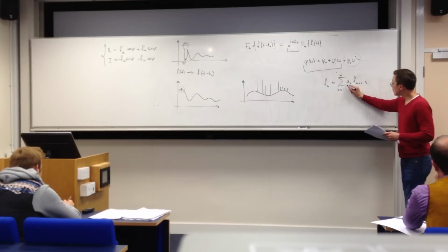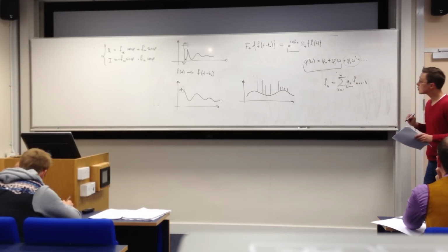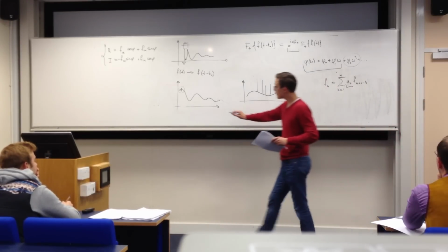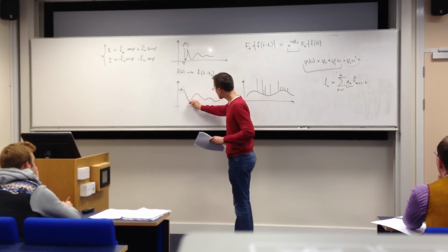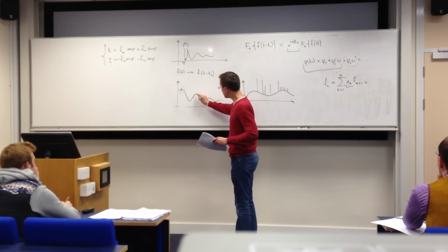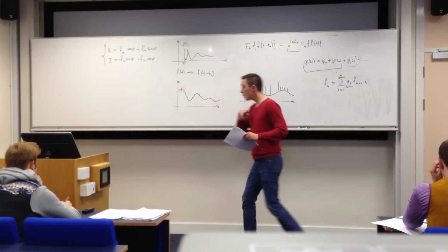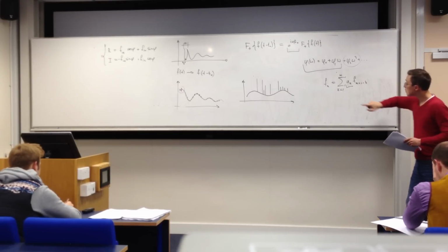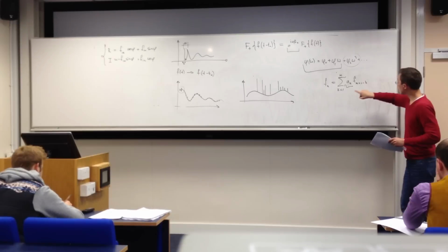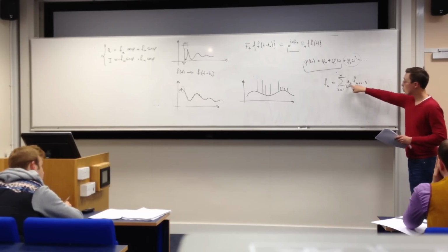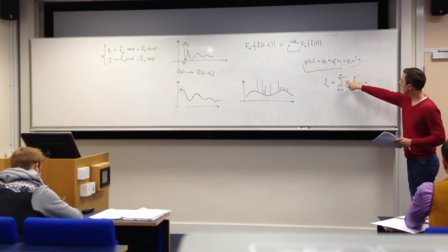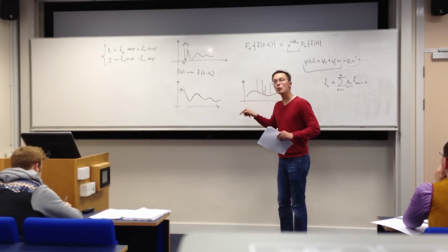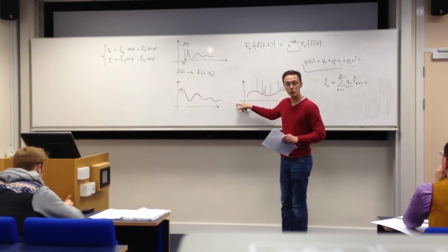Well, how do we find out what these coefficients are? This is what the rest of the signal is for. We can in principle start here at these points. The results we know. This would mean a system of equations for known results from a known training set for unknown coefficients. So we can determine these coefficients from the part of the signal that we know about, but then use these coefficients to predict the signal that we do not know.